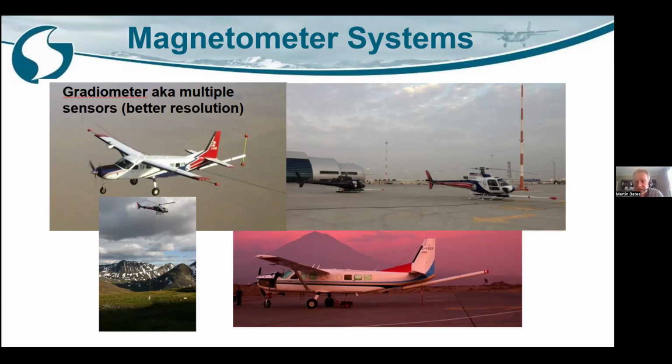With the helicopters, you can see if we want to fly lower, then usually our surveys we're operating at around 80 to 100 meters above ground in a fixed wing airplane. We don't really fly a lot lower. In a helicopter, when you're flying in rugged terrain, it's harder to stay close to the ground. You can imagine if you've got a hill coming, you can't really scud along at 60 meters above the ground if there's a mountain coming up, because you're just going to fly into it. So you have to start to climb up and over, and that reduces the resolution of your data in rugged areas. So if you really want to get good data in rugged areas, a helicopter is your better bet.